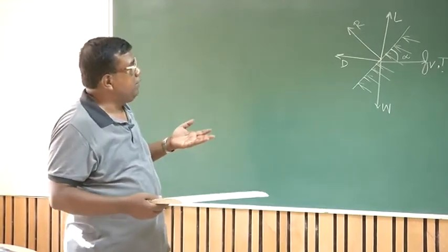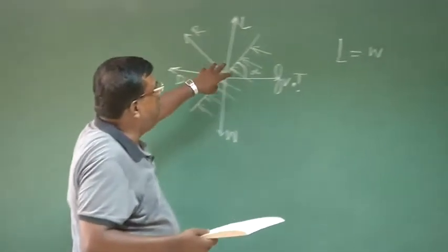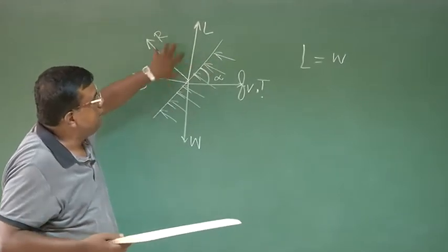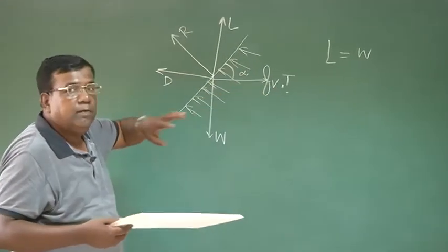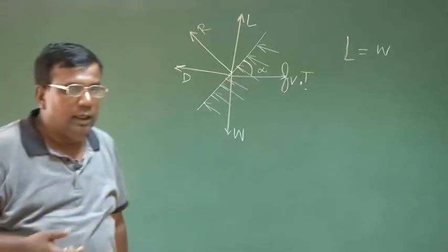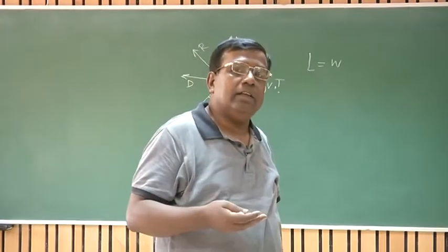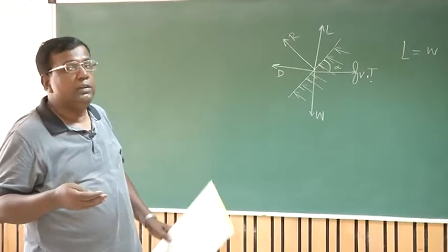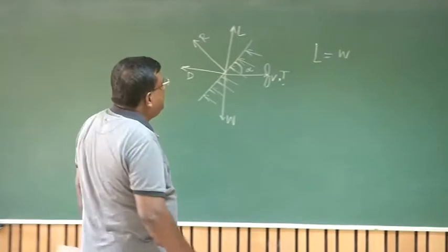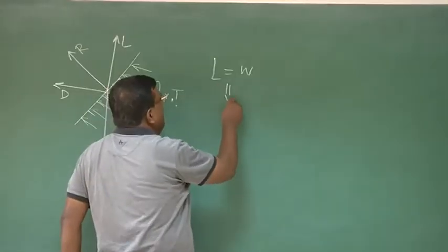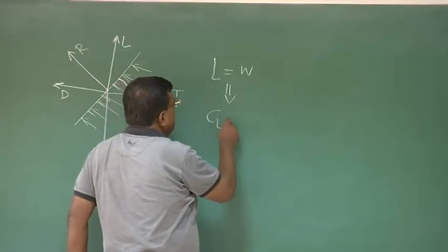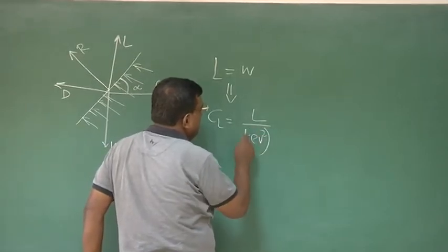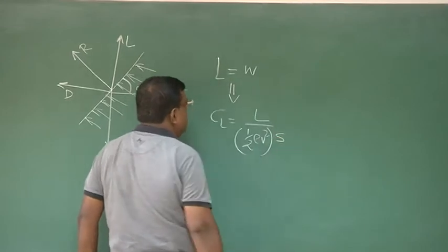And before we go to aspect ratio, we will have a relook here and try to see how I translate this to a pilot in terms of flying the machine. Because I always said, whatever aerodynamics, whatever flight mechanics we do, finally I have to translate this in terms of a language which a pilot can understand. Then from here we realize that we will be operating in terms of CL, which is nothing but lift non-dimensionalized by dynamic pressure times S reference.